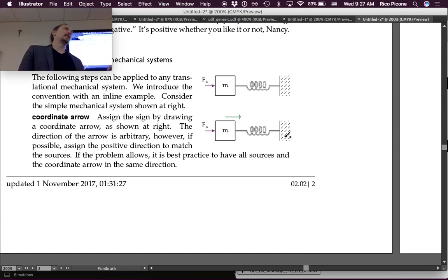So we're going to draw our linear graph in that orientation. It'll just help us out. I think it's a little easier. So we draw with the ground on the right, and then we have two distinct velocities, I claim. One is the ground. The ground is always a distinct velocity, so it's always a node in our graph. And then we have the mass, which also has a distinct velocity. The mass has a distinct velocity. The ground has a distinct velocity. There's no other one, really, because the spring connects in between those two.